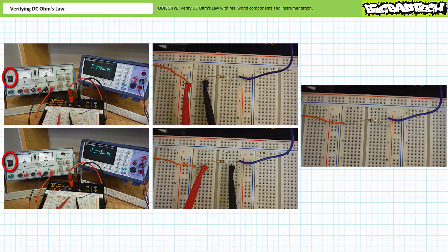In this scenario, however, the source is clearly on. However, we're still not observing any current. No current is a clear sign that there is an open somewhere in this circuit. You know, the circuit has the positive terminal of the source landed at node 5A through E. One terminal of the nominal 560 ohm resistor also landed at node 5A through E. The other terminal of the resistor landed at node 5F through J across the ditch.